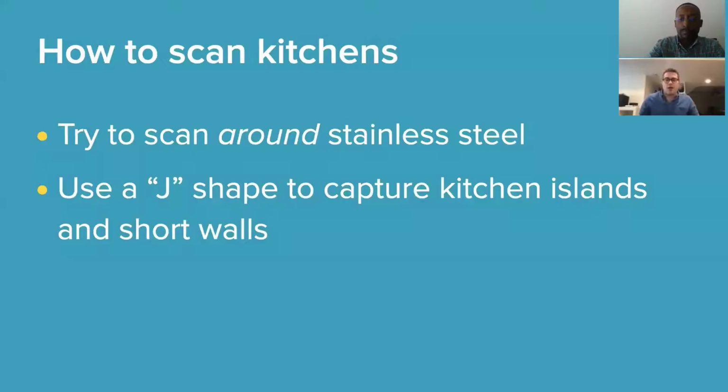Now, since I know a lot of you are going to be scanning kitchens and baths, given the nature of your business, there are a few things to keep in mind when you are scanning in those types of spaces. Reflective surfaces can confuse your lidar sensor. So if you imagine it's shooting out that invisible beam of light and measuring how long it takes to come back, if it's a highly reflective surface like a mirror or stainless steel appliance, that can confuse the sensor and then can interfere with the accuracy of your scan.